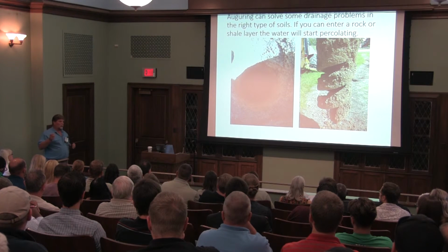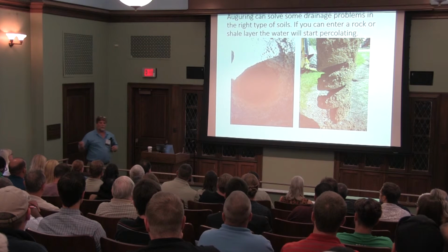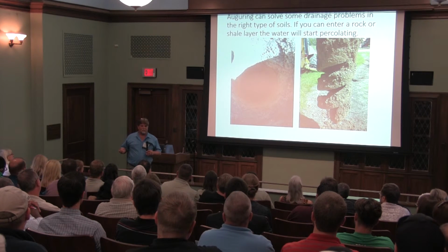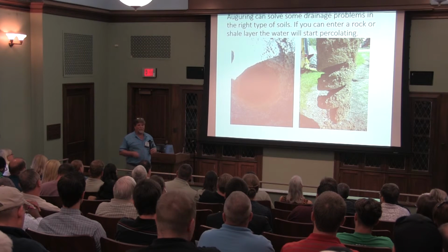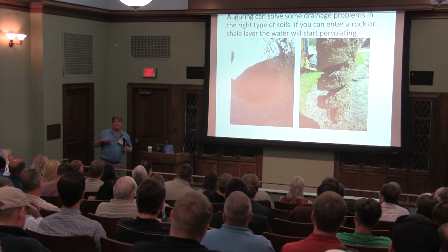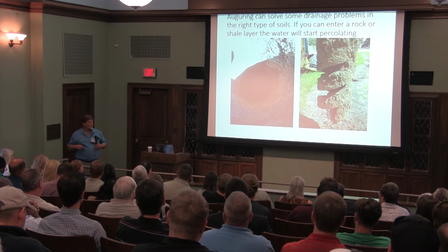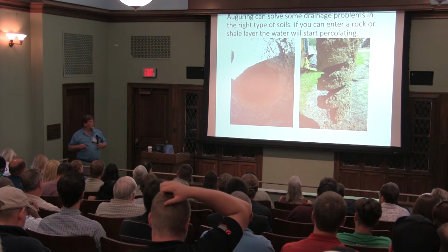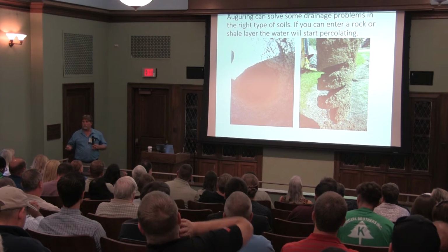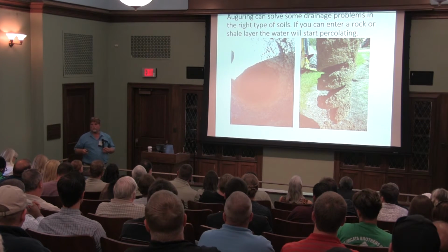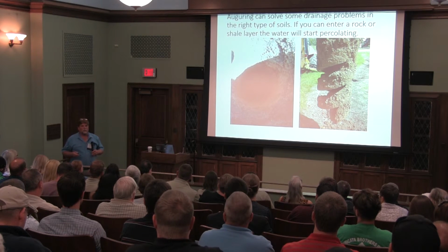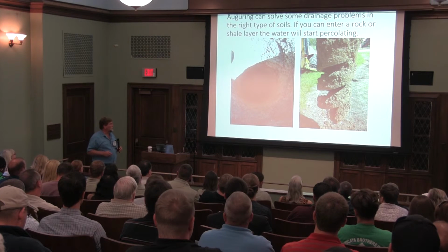If anybody's ever drilled a well, your house wells, you got good water, shallow, it's 120 feet. Okay, I still got 90 feet of rock for the water to get through before somebody's going to pull it out of the ground. Obviously they go down to about 300 feet to build a house well, and if you go much below 300 feet in most areas, you end up with bad water that's got salt in it, in western PA, depending on where you're located.